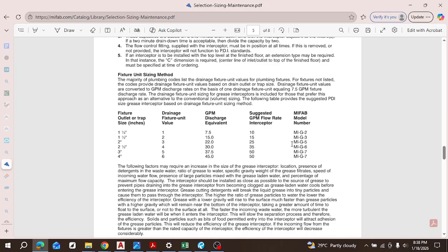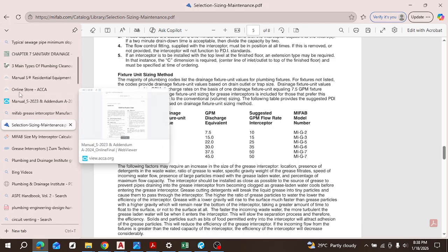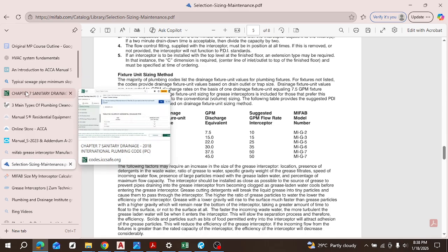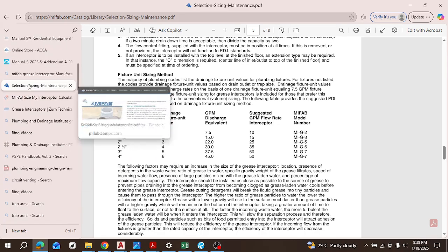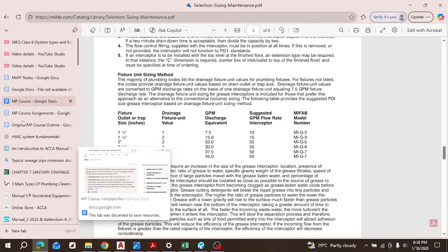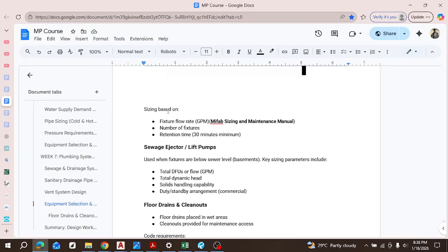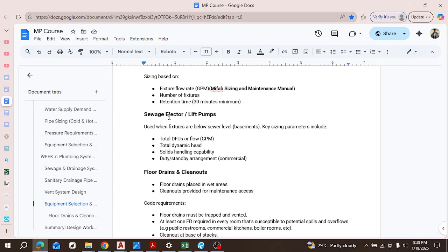I saw some people that used volume, right? But using the volume of the sink or the fixture is not very efficient because you can't always know the size. There are different sinks, and each of them has different sizes. So you can't always know the size of the sink except you're on site. This is even better because they all have fixed trap sizes, right? So it gives a more informed guess. Okay, so that's how you size.